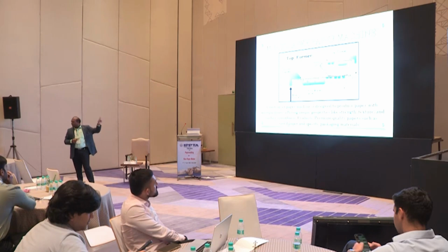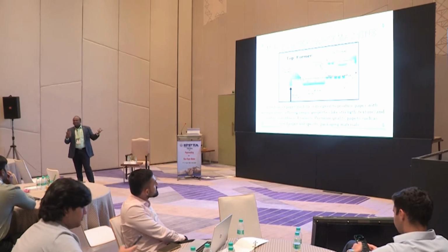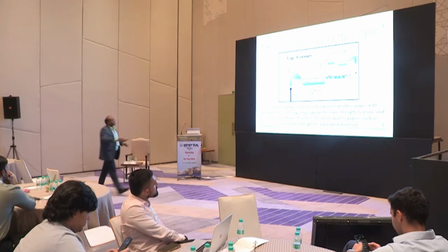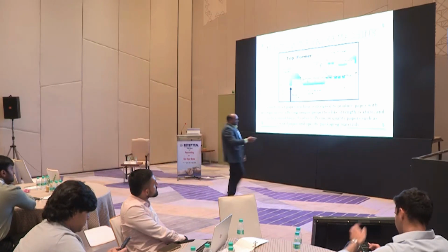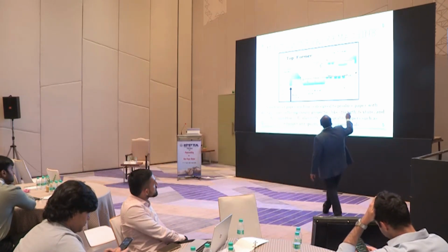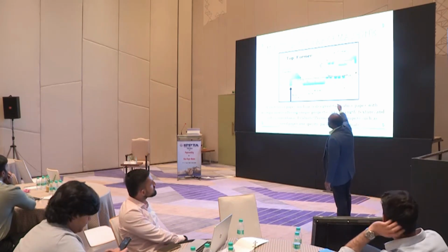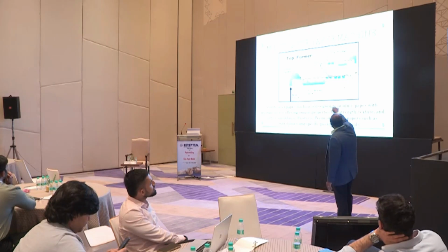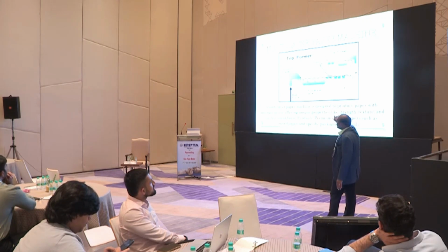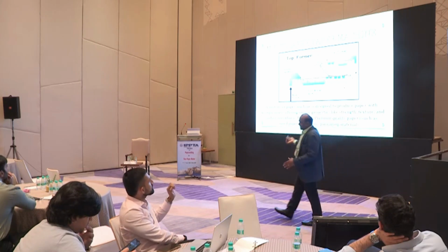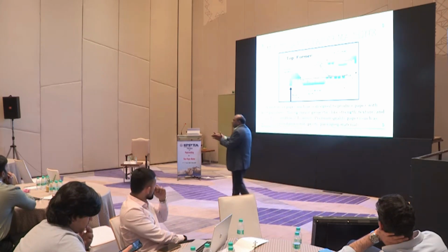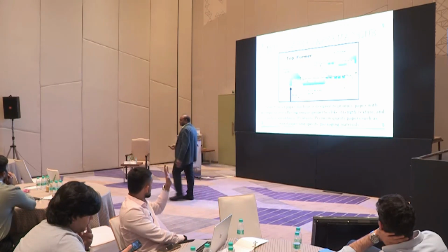These are two different formers and two different layers. There you can see a head box in the top former. Here one head box is there, and from that one couch roll is there, a separate wire part is there. So from that, one layer of the paper will come and meet at the exact dry line point of the middle of the Fourdrinier paper machine, and together it will go to the next press section where the sheet gets consolidated further.